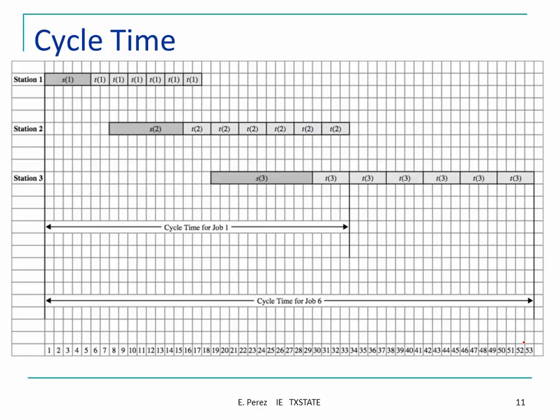Okay, so the cycle time for the first job actually is not the 55 units. That will be the cycle time for processing all the parts. The cycle time for the parts actually is the average of each one of the cycle times individually. So for example, you have the cycle time of the first part that is going to be this line right here, 33. Then you can compute the cycle time of the second one. That will be 37. The cycle time of the third one, 41, and so on.